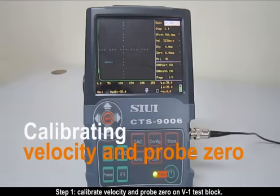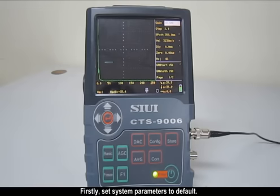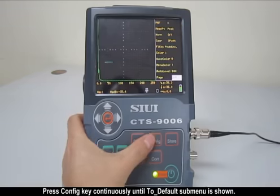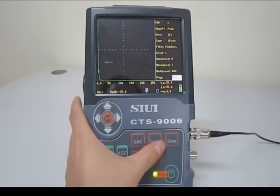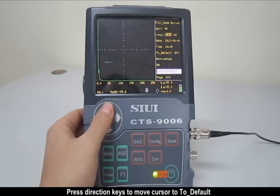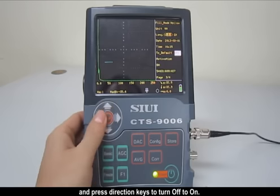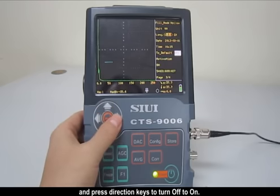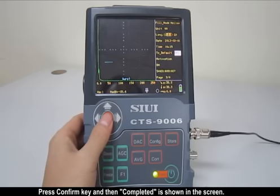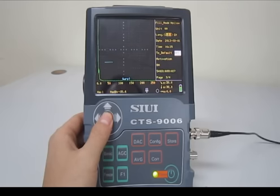Step 1. Calibrate velocity and probe 0 on V1 test block. Firstly, set system parameters to default. Press Configure key continuously until the default submenu is shown. Press direction keys to move cursors to default, and press direction keys to turn off to on. When Sure is shown on the screen, press Confirm key and then Completed is shown on the screen.